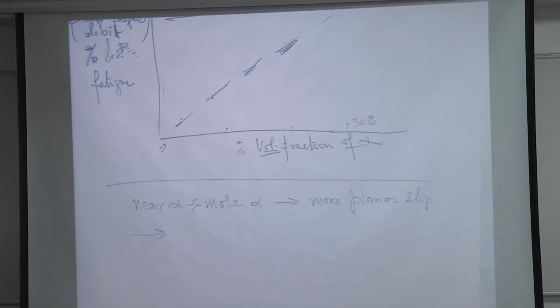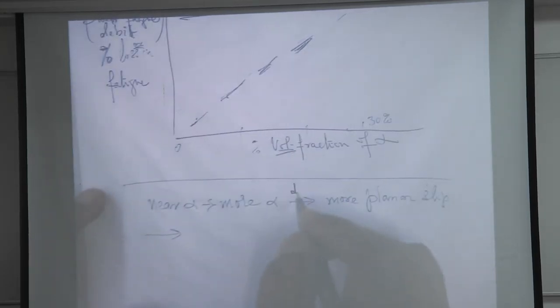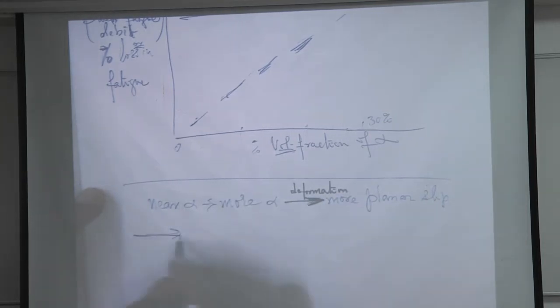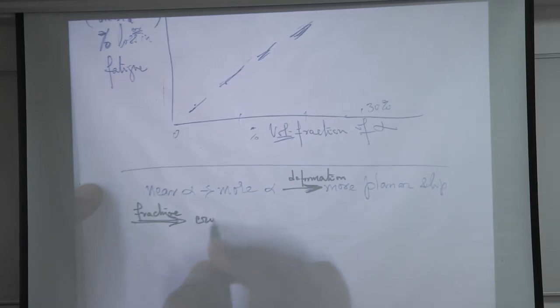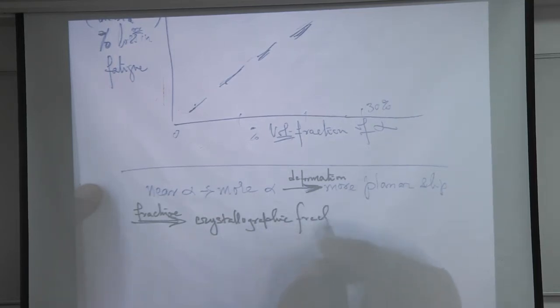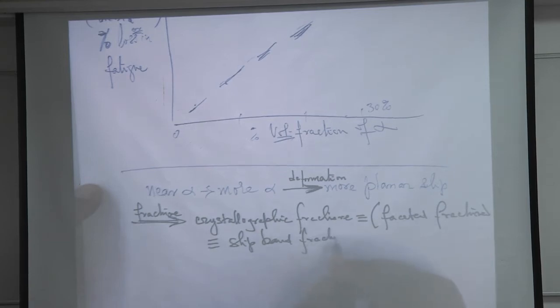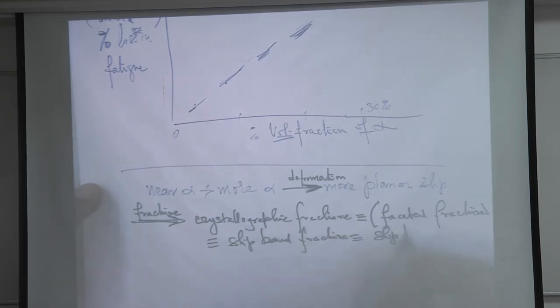In terms of fracture, that means it is more crystallographic fracture, which is the same as faceted fracture, which is also the same as slip band fracture, slip band decohesion, all those different terminologies.